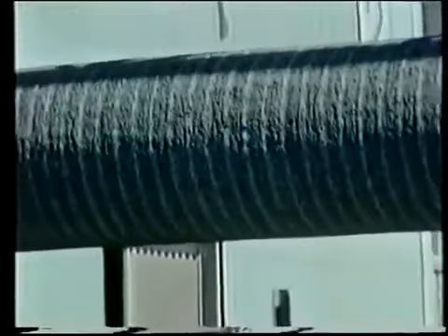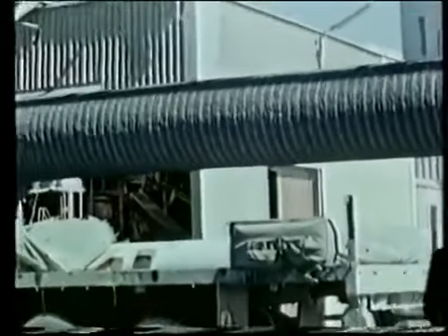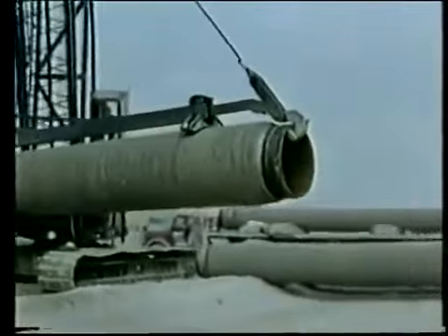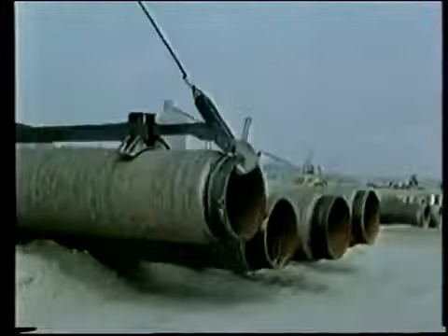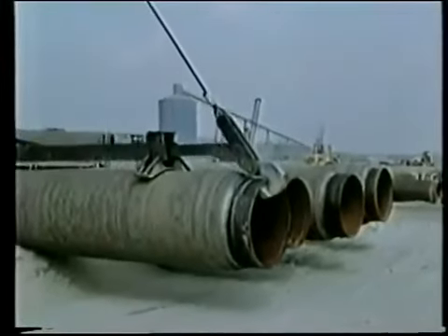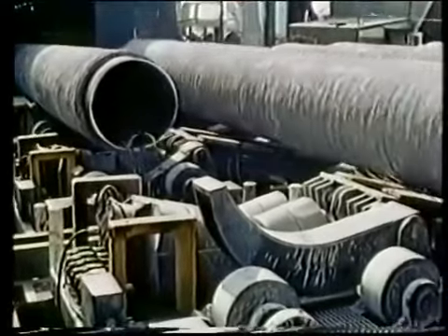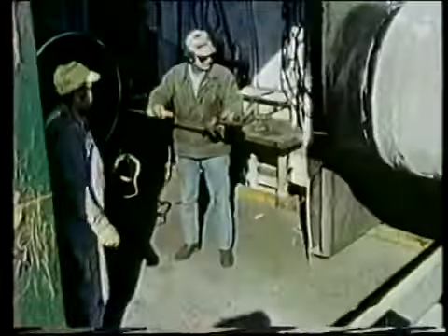The pipes are coated, beveled, and carefully lined up before going through up to 6 welding processes. Rigorous checks are made at each stage, including the use of X-ray film. The joins are then wrapped with an adhesive primer layer, and a steel sheet is strapped over them before they're filled with melted mastic and finally laced up ready for use.